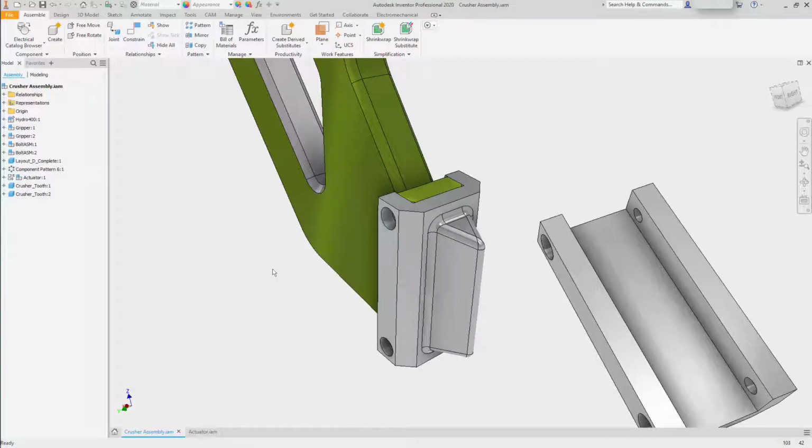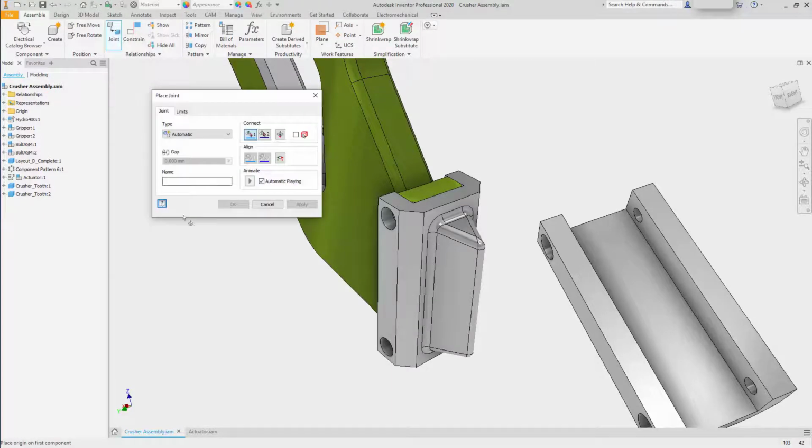The other primary system inside of Autodesk Inventor for connecting components is joint. Joint works on a different way of approaching things. The joint can apply different types of connection, each removing different levels of degrees of freedom based on origin points. So rather than strictly picking faces or edges or curved edges, if I hover over a face, I can see any given face has 9 different locations. The center point, or the centroid of the face, the midpoint of any edge,